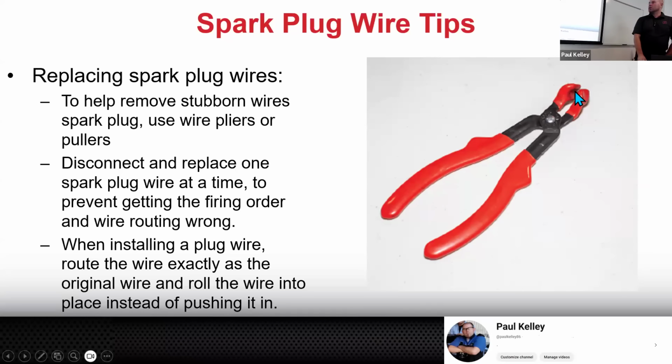I'm not trying to do it anymore. These pliers are pretty nice. You can grab them, twist them, and pull them off at the boot where it's kind of stronger, right? But the other thing is, I have a pair of these that are even cooler that have a little wire, and the wire has a little alligator clip, and I can clip them to ground. That way, if I want, I can pull spark plug wires off while it's running and not lose any more hair. I don't have much left. I have to retain this. So if I pull it off and the path of least resistance is no longer through my body, it's through the little lead that's connected to ground, it'll actually not shock me. That's nice. I like that.